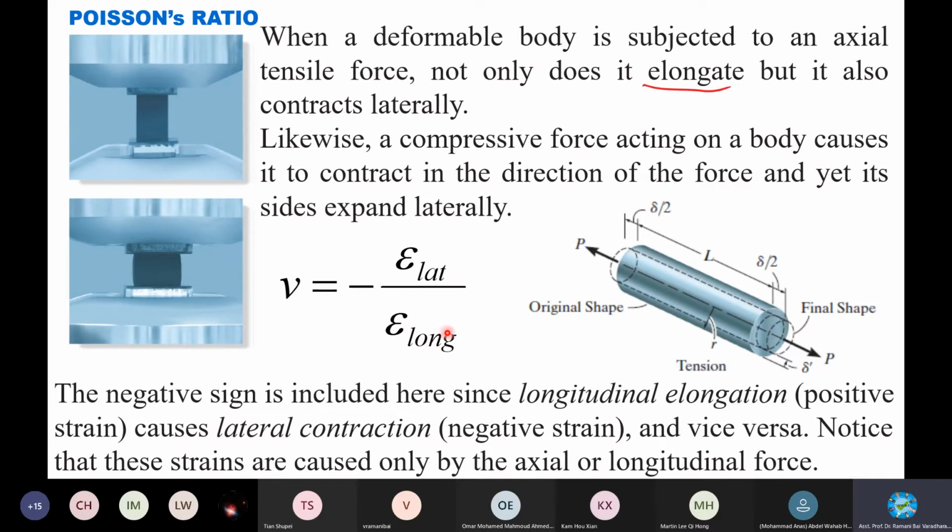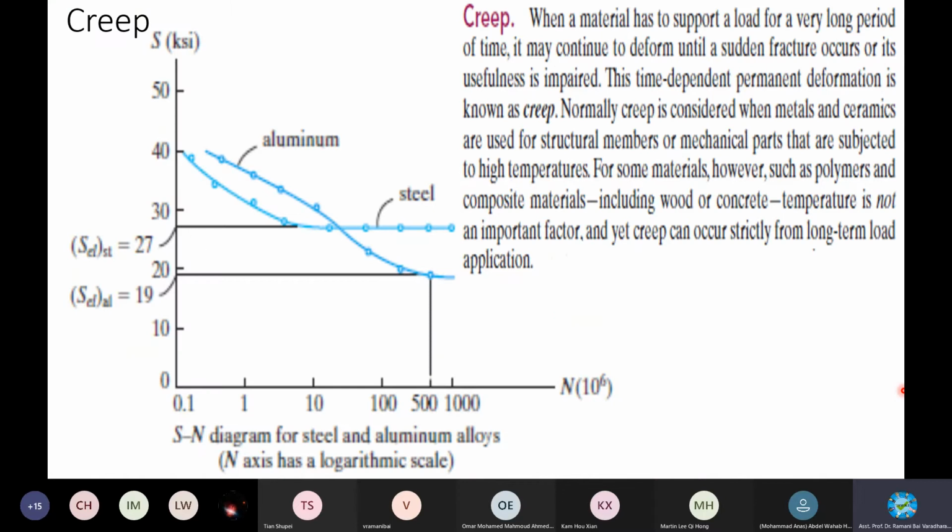So Poisson's ratio decides the overall deformation, right? Last time, Young's modulus gave you the coefficient for the elongation, and the shear modulus, the modulus of rigidity, gives you how much is sheared. But this one gives you both the cross section and also the lengthwise deformation.